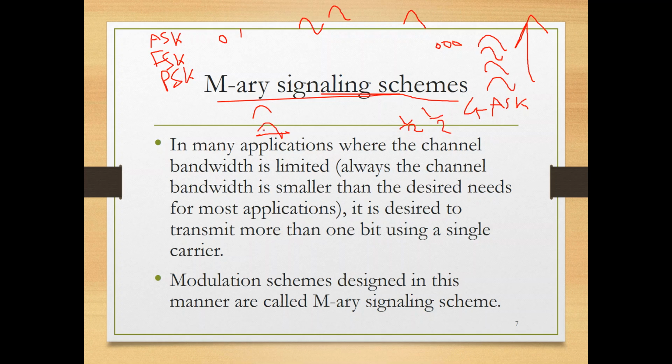But when the number of levels increases to 4, and you sent this, the third one, what's the possibility that you decode this correctly? 1/4. And what's the possibility of making error? The rest, 3/4. So from error equal 1/2 to error 3/4. Which one is more prone, more susceptible to errors? The second one, the one that has more number of levels. Is it clear now, the trade-off?